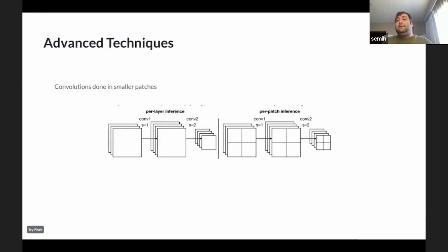And the way TensorFlow and many other machine learning frameworks work, they first allocate the memory for your output and then keep writing there, which is a valid operation. But if you are on an MCU device, your memory is probably not going anywhere, that's the only thing that your MCU is running. So if you can convert this training process to, instead of matrix-based operations, operate at the input level for the matrix, and then just write it point by point, you don't have to allocate your output layers all at once. And by this, you gain a lot of flexibility on the memory allocation.